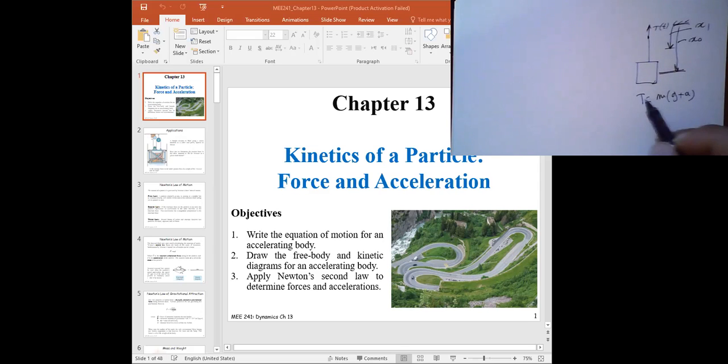So later on, you will learn feedback control systems and how you actually control stuff. When you move an object, you basically control T as a function of time, by means of controlling the voltage on the motor. You control the tension. Tension will control the acceleration, acceleration will control the velocity, and the velocity will control the position. Ultimately, you're not really controlling the acceleration, you are only controlling the position.